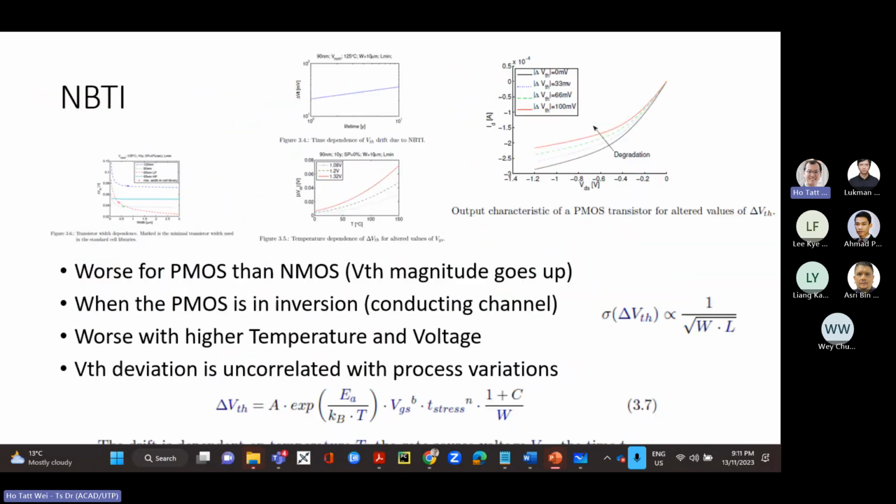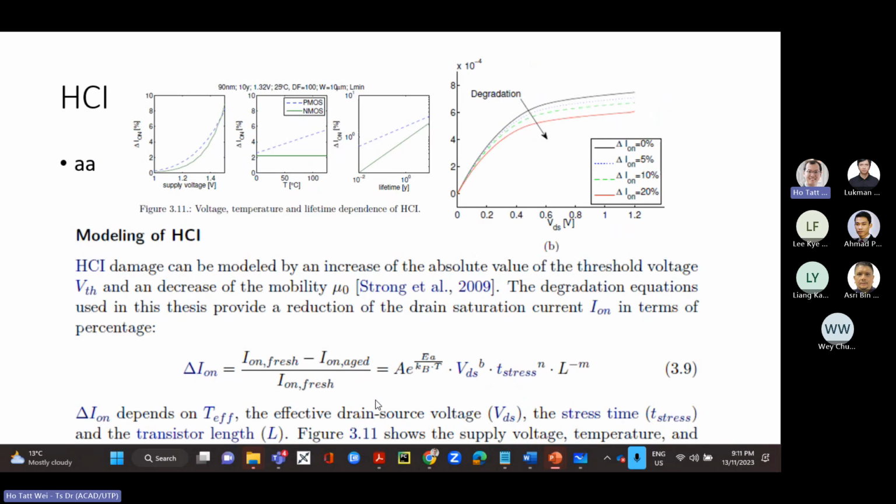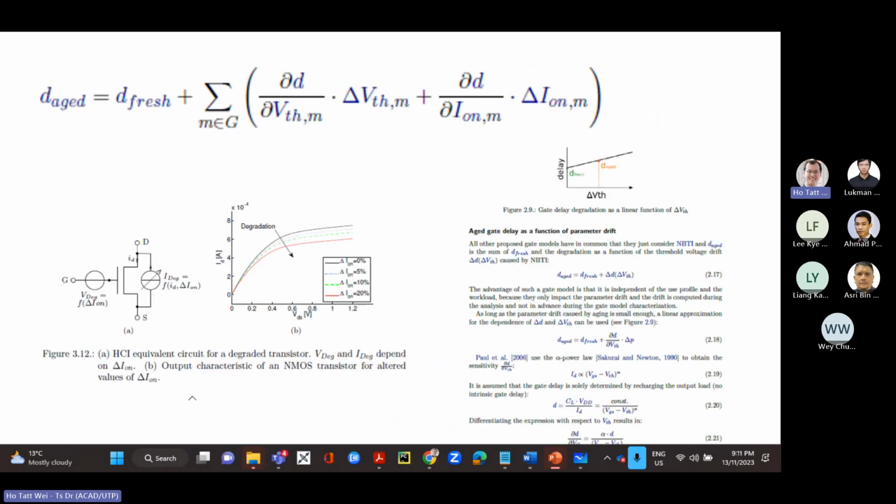Second, I would need you to be able to estimate that. Like I said, you can estimate the NBTI by a change in VTH. You can look up all these constants in the thesis. There's a paper by Massey in 2004. Go read it, and then learn how to plug in those values, get some number here, and then the ION, and then you can reference this equation.